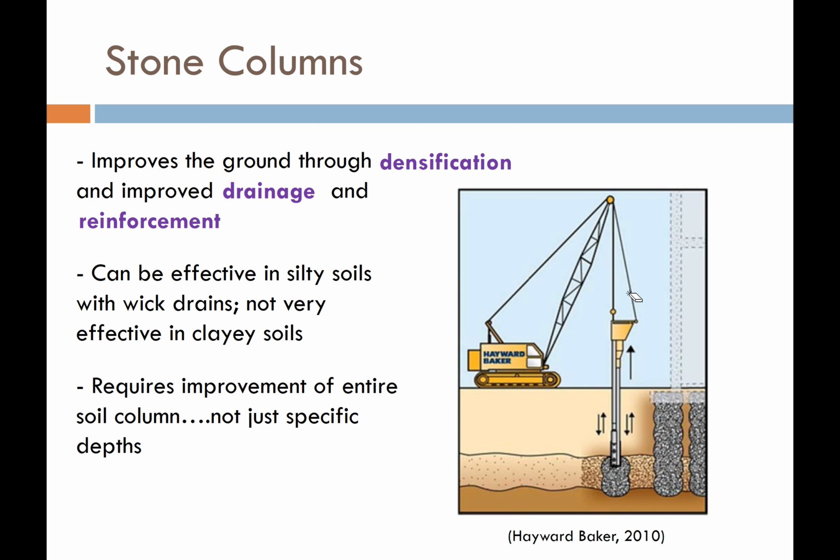As our vibro-float goes up and down, the gravel comes down through the chute and exits into the void space that's created by the vibro-float. And so what we end up with is a column of compacted, angular, sharp gravel up and down, and we can then do these columns on a grid or a pattern beneath our structure or site.